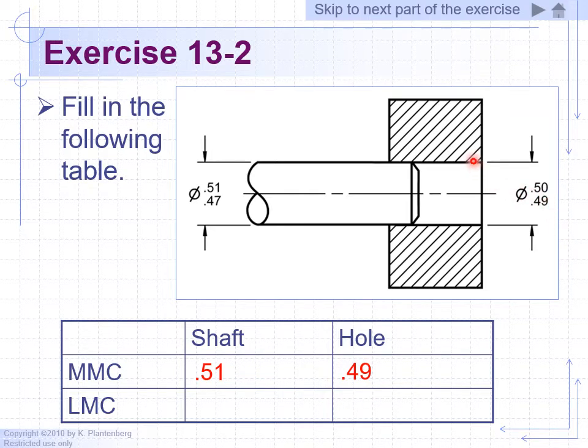If you were to drill up to a 0.50 diameter, then you're removing more material. So that's when you have less material, when you drill at the maximum diameter. When you drill with the smallest diameter hole allowed, you leave behind more material. So the maximum material for this block, or when it's at its heaviest, is when you're dealing with the smallest diameter allowed of 0.49.